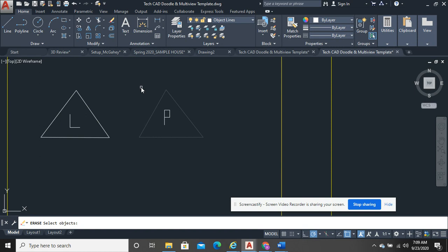It's highlighted, so how do I get to the next option? I right click, okay? At the same time, I can click the thing I want to erase, and I can also click erase, okay? So again, you can do command, then select, or select, then command. Either one works, okay? So in this case, I'm going to go ahead and select the thing I want to change. And the thing I want to do, remember, I'm trying to isolate this bottom piece so I can remove it.